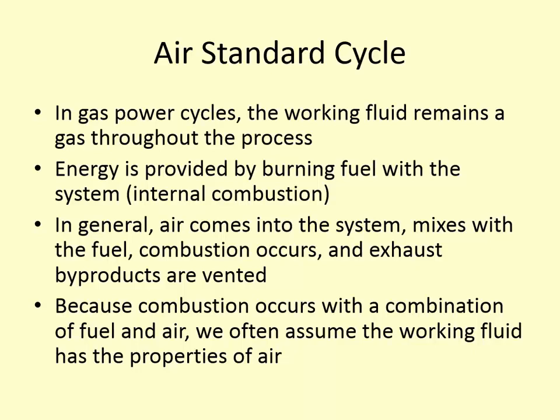In gas power cycles, the working fluid is a gas throughout the process, but it's a combination of many different things. The gas is vaporized as it enters the combustion chamber, and it's mixed with air, and then the exhaust gases that are a byproduct of the combustion process are also mixed in with air. So even though it's not completely air, we can make something called the air standard assumption, which we'll talk about on the next page, which allows us to analyze these gases as air.